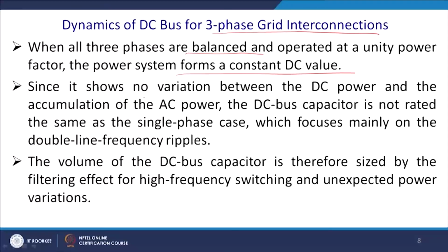Since it shows no variation between the DC power and the accumulation of the AC power, the DC bus capacitor is not rated as in the single phase case, which focuses mainly on the double frequency ripple. That is something quite important in the case of the 3 phase system.